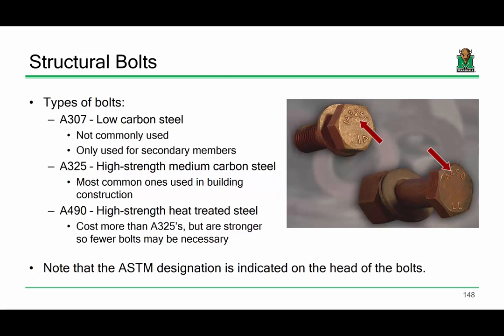I'll say a couple other things. Typically in bridges, you're pretty much exclusively using A490, especially on splices, because of the presence of fatigue. Typically, whenever fatigue's involved, your connection requirements jump through the roof. You end up needing more connecting elements or more inches of weld or whatnot. And so that just sort of is what it is. In buildings, you can see a mixture of both.